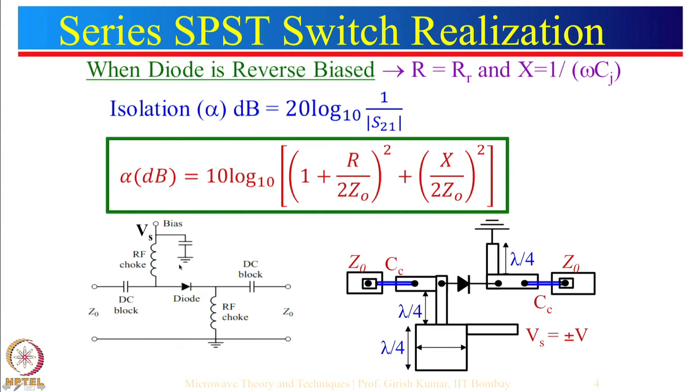Don't take a very large value of inductor, because at very high frequency these inductors may act as a capacitance. So why do we need a large value of inductor? The reason is that if we don't put a large value of inductor, then at AC frequency, if this is not very large, this will provide a path to the ground here. Remember, for AC, DC voltages act as ground. So the AC input here will get short circuited through this particular inductor. Similarly, over here we need to put a large value of inductor so that at a given AC frequency this inductor will act as an open circuit.